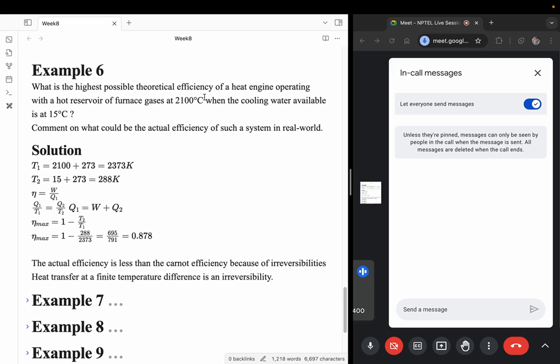So here comes the trade-off. If you want to have higher theoretical efficiencies like the Carnot cycle, you need to be operating very slowly, which will not meet your requirements. And if you want to speed it up a little, then you are doing it with much less efficient processes. So this is where the trade-off comes: the speed versus the efficiency. If you want higher speeds, then your efficiency drops. And if you are at lower speeds, your efficiency increases, but then that is not useful to us at any point of time.